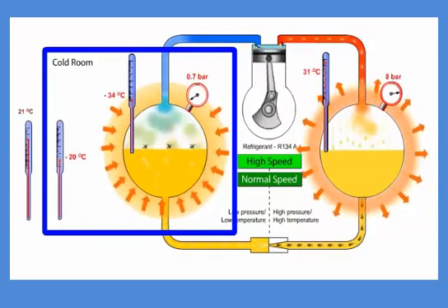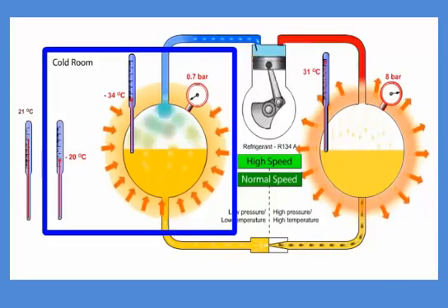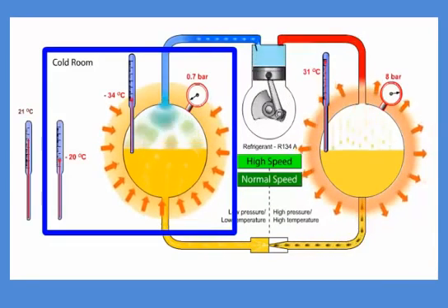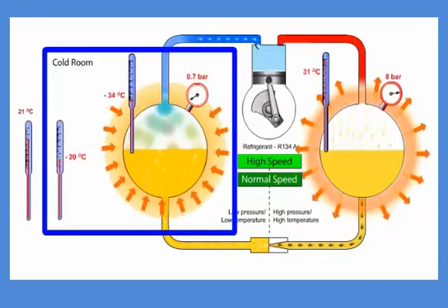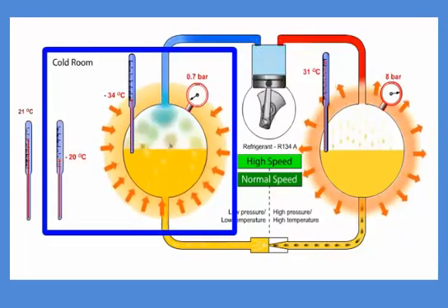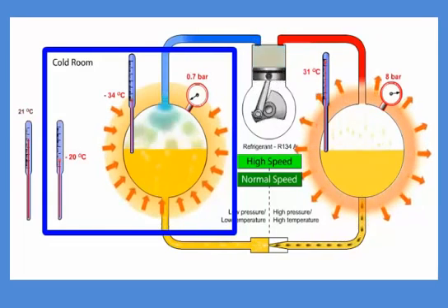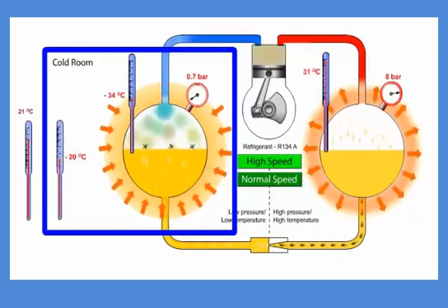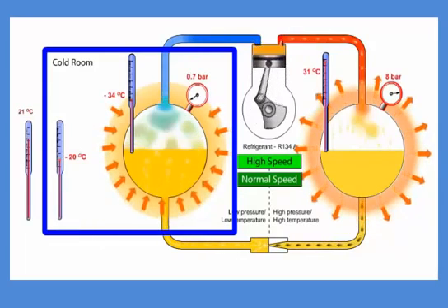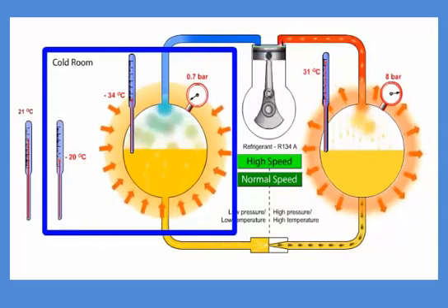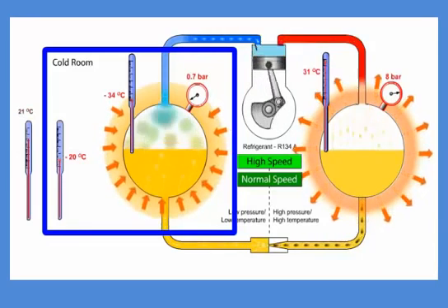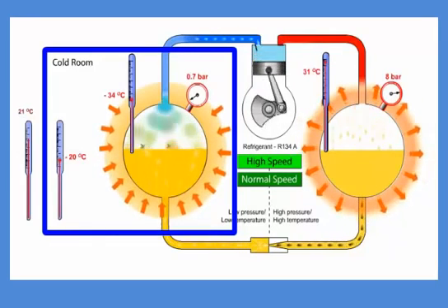A drop in room temperature will also result in an increased temperature difference between the room temperature and the ambient temperature outside the room, causing an increase of the heat transmission through the room wall. A new equilibrium will now emerge when the two heat transmission flows equalize. The result is a lower room temperature. In this example, the temperature is reduced from minus 16 degrees Celsius to minus 20 degrees Celsius.